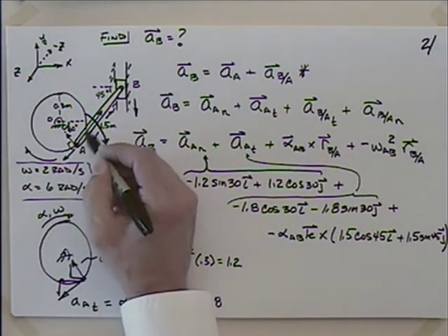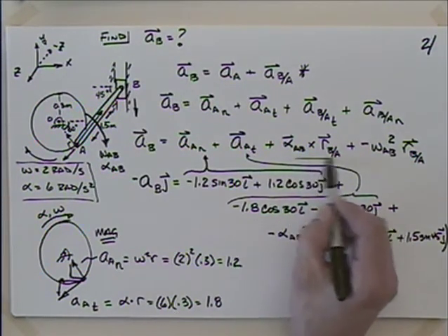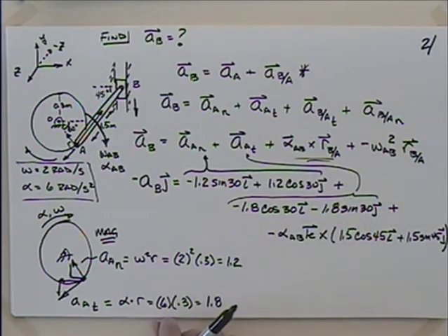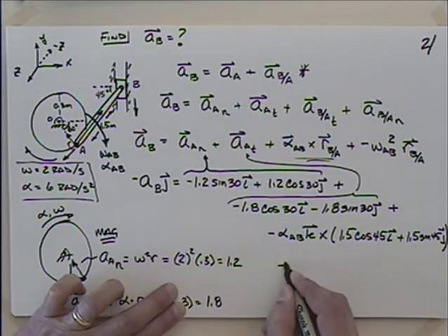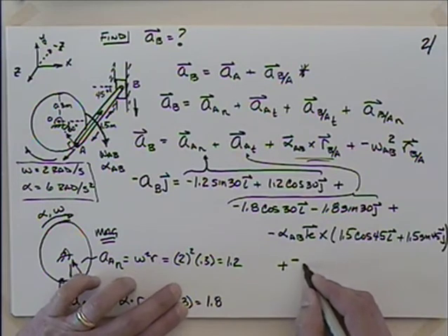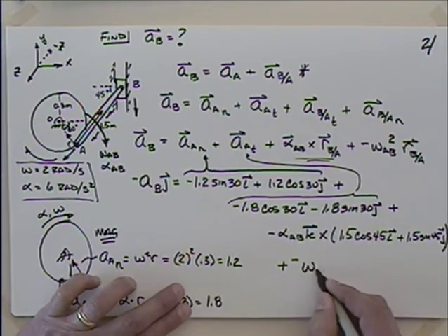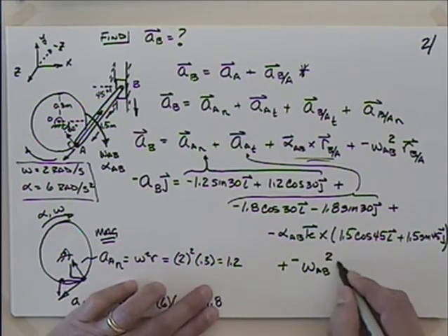So that's just breaking this link into i and j pieces. Okay, so that's that one done. And then I have one more piece. What's that? I'll have this plus a minus, because I have that minus omega AB. And let's see, I don't know omega AB, so I'll just fess up to that. Omega AB squared times R. Okay, I got that same thing here.